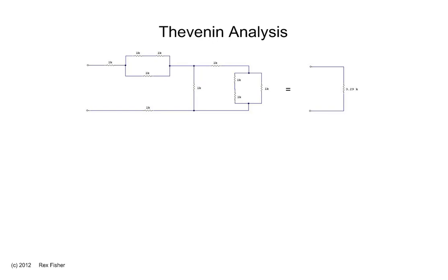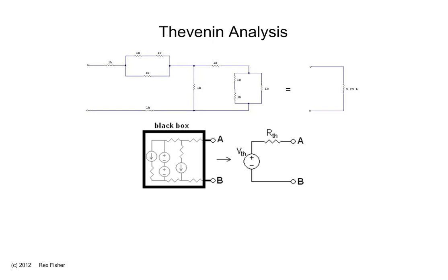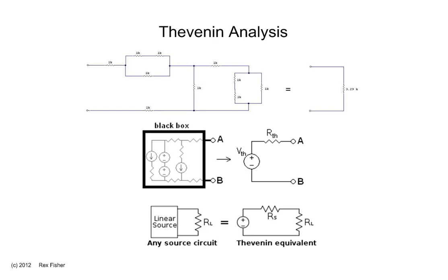Any linear network of resistances can be reduced to one equivalent resistance. Thevenin's theorem converts a complicated circuit into a simple circuit with one voltage source in series with one resistor. When the load is connected to the Thevenin equivalent circuit, it behaves exactly like it did in the original circuit. That load can be anything from a motor to a computer chip.